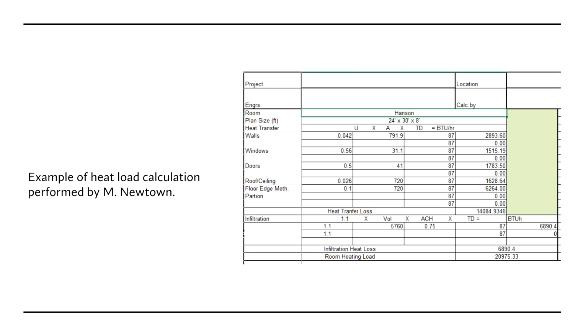So this isn't room by room, but normally I would calculate the energy transfer from the indoor space to the outdoor space, room by room, because I'm going to look at what my zones are, and I'm going to try and size my indoor units to match my zones or the spaces that you're living in. So it's important to do it that way. If you ever need some help, don't hesitate to call us. The college always loves a challenge for students to work on, and this is one of those things that we can have them do.